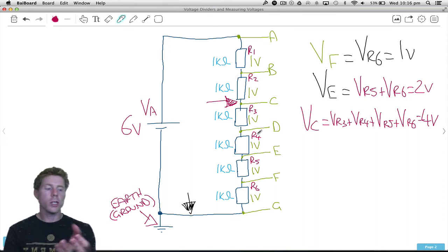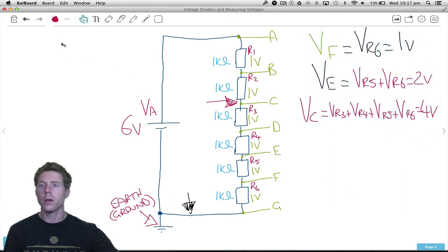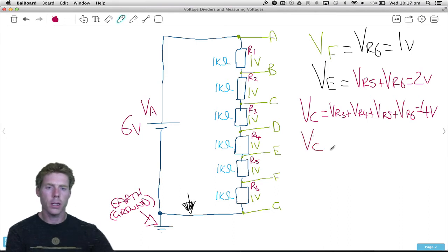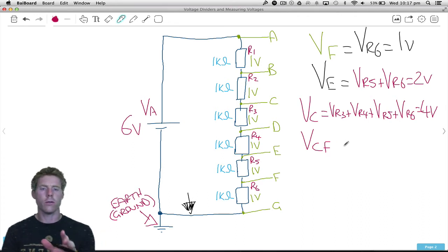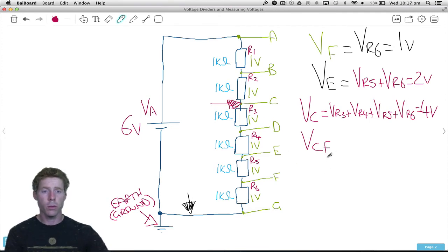But what are all these ones? I've only been giving you one letter. What if we put a second letter there? Let's just move that up. Well, I'm glad you asked. So let's say I want, okay, what is VCF? So there's 2 letters there after the V. I want to know what is the voltage at C. My reference point, because I've given you a second letter, that is now my reference point, and I want the reference point to be F.